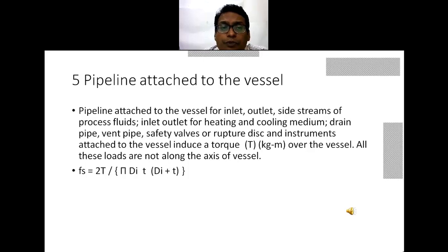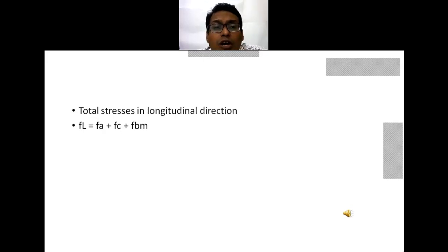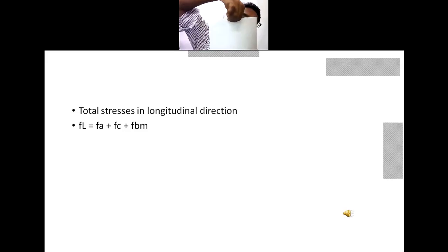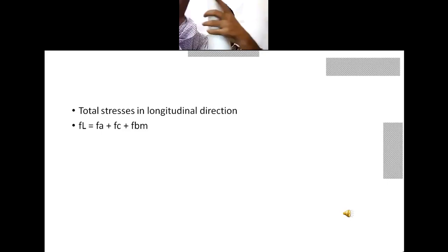So the actual stresses in the longitudinal direction: first, the longitudinal stresses because of the internal pressure. When I am pulling in this direction, my longitudinal stresses are here. Now the weight of the vessel has to be taken into consideration.